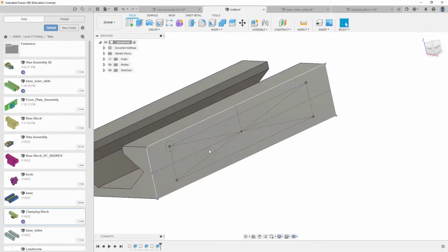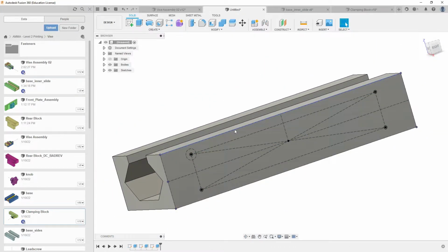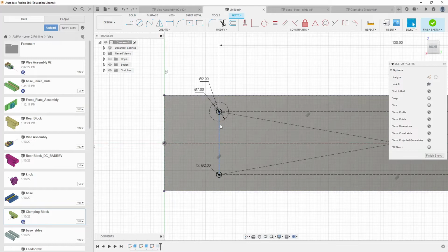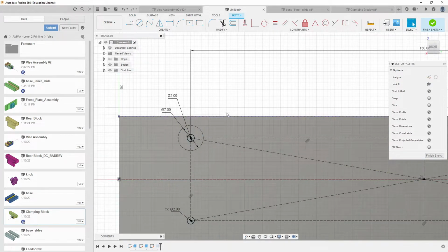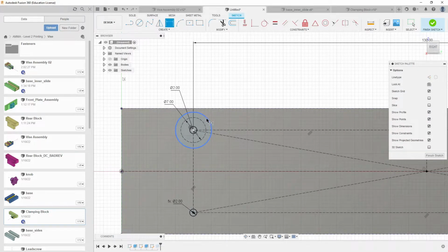There's our holes. So, like I said, what I'm going to do is, if we got 10mm in there, the heat set inserts are about 5 or 6mm deep. I don't have one near me to measure right now this instant. So what I'm going to do, though, is I'm going to go ahead and take this one right here. And actually, you know what? We can leave that one there because it's good for our purpose. But I'm going to add in another one. We'll make this 5.